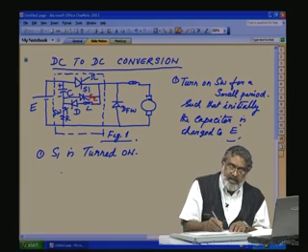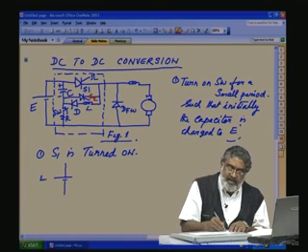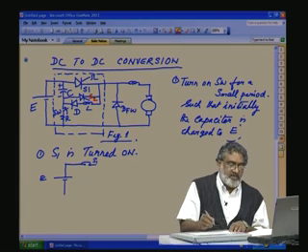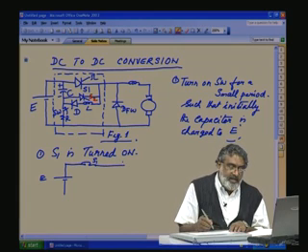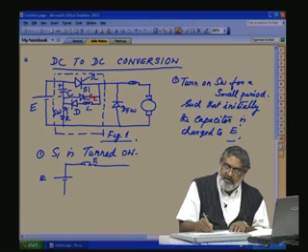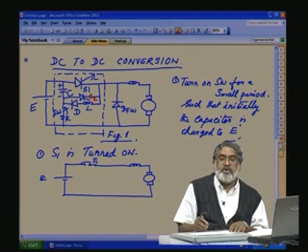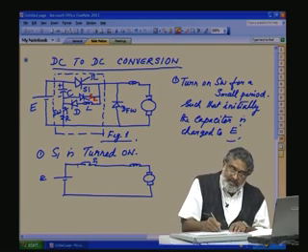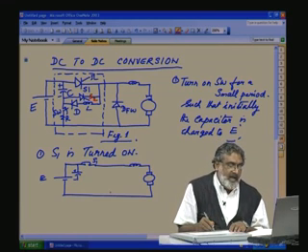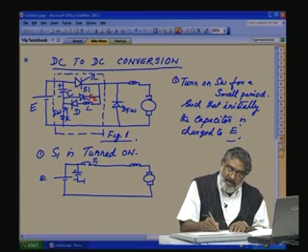See, the circuit I will draw here. You have E here, the thyristor is turned on. So, this is a turned on switch, S1 is on. The diode is reverse biased, so that will not come into the picture. You have this load. Now, there is a capacitor here, charged in this direction, and there is this diode and L.